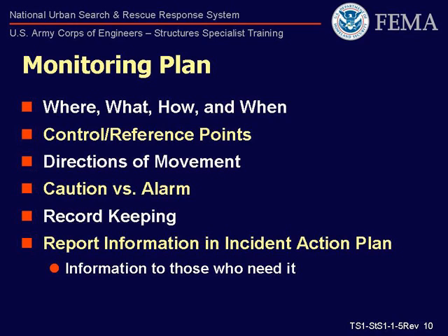A monitoring plan is going to clearly lay out the details of what is being monitored. It will clearly communicate what items on the site are being used for reference or control points. It will typically have some note to describe the anticipated direction and magnitude of movement. It will also provide the range of displacement that is to be considered dangerous.